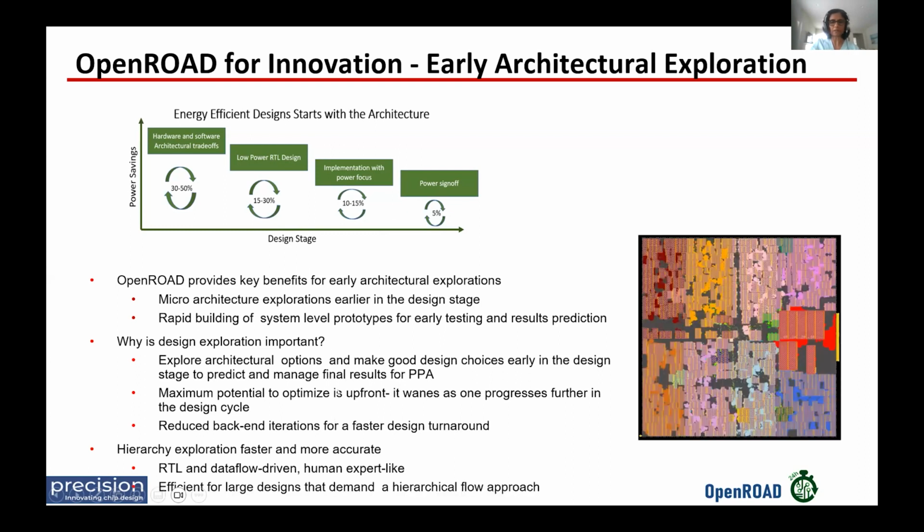And this is just a picture on the right to show how we do early RTL hierarchical exploration. You can build out very specific hierarchies that have been proven with physical design implementation very rapidly using OpenROAD, and this enables the RTL designers to build out very good logical hierarchies in their Verilog.